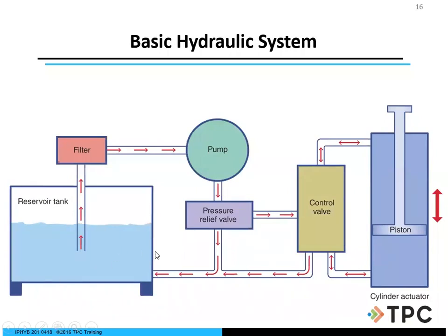Reservoirs are huge. Knowing what your reservoir is made up of, you have baffles inside of reservoirs. We have our hydraulic fluid in there, right? But is our hydraulic fluid clean or dirty? So we need to look at the filtration. Filtration is huge. Like I said at the beginning of the seminar, if we don't have proper filtration, then we're running this contamination all the way through our system, decreasing the life of our components, our valves, our pumps, and so forth. Then you're going to get a blockage somewhere in the line, creating a lot of pressure somewhere. We're not going to get our flow rate, and we're not going to be able to do the work that we need to do.